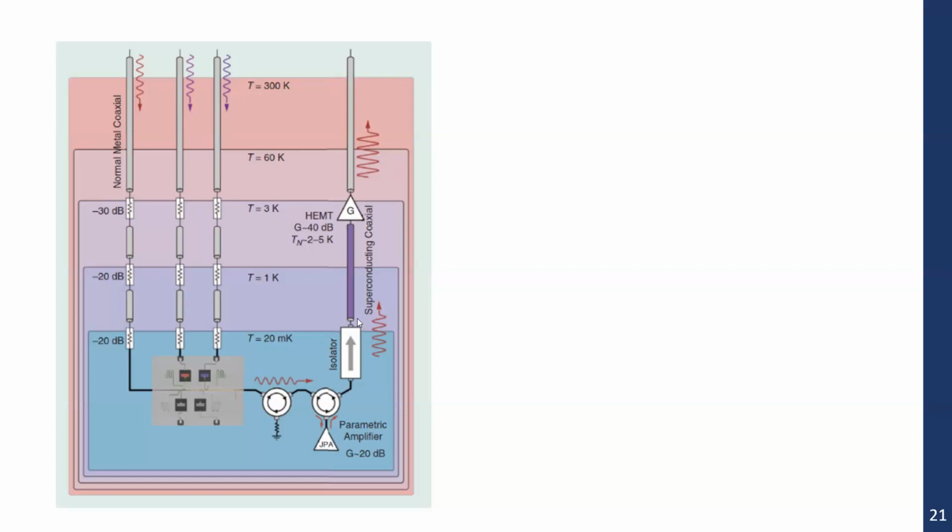So we cannot put these attenuators, and instead we need to amplify the signal. That's why people use these different parametric amplifiers which work in the reflection mode. So we need to use some isolators and circulators.